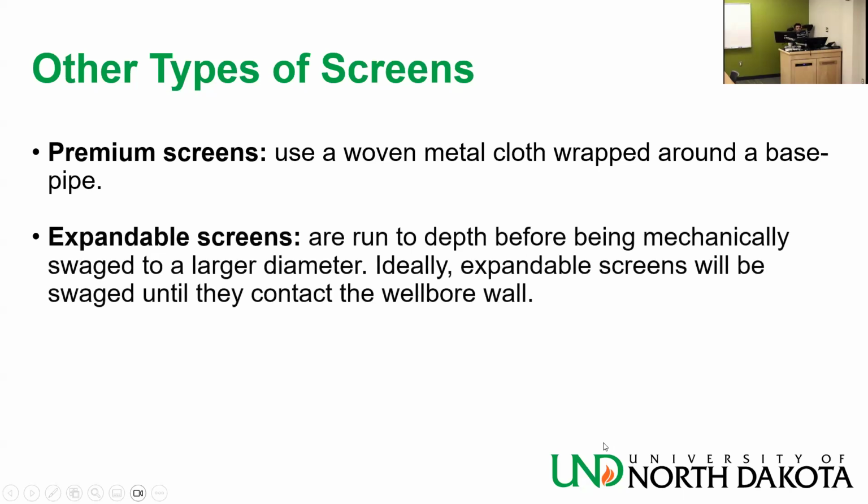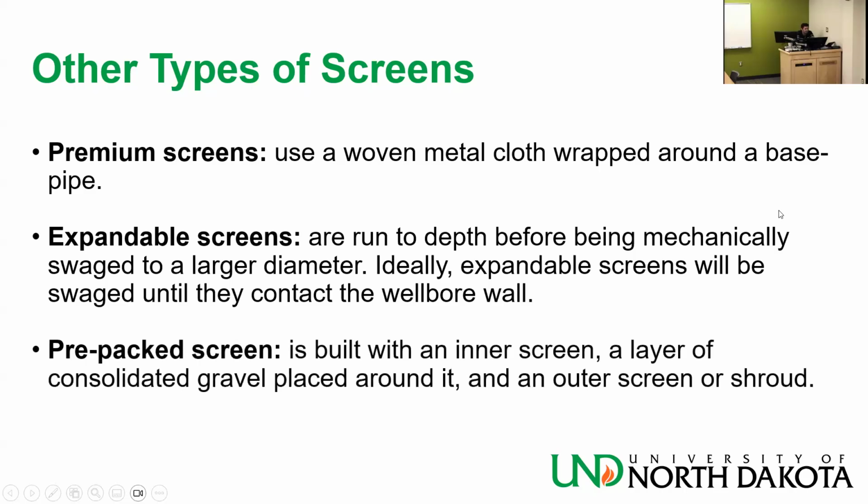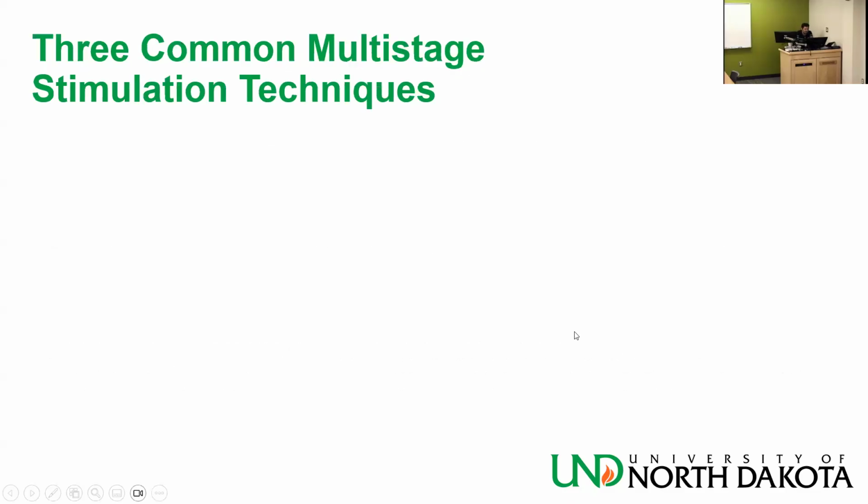Expandable screens are run to depth before being mechanically swaged to a larger diameter. Ideally, expandable screens will be swaged until they come in contact with the wellbore wall. Pre-packed screen is built with an inner screen, a layer of unconsolidated gravel placed around it, and an outer screen or shroud.